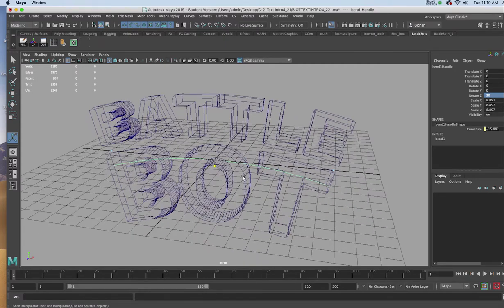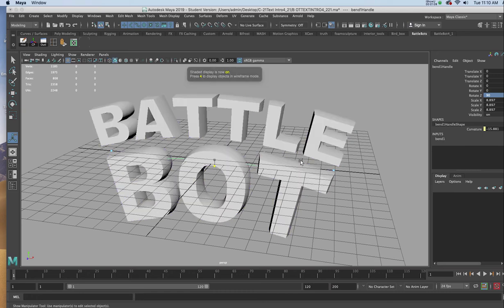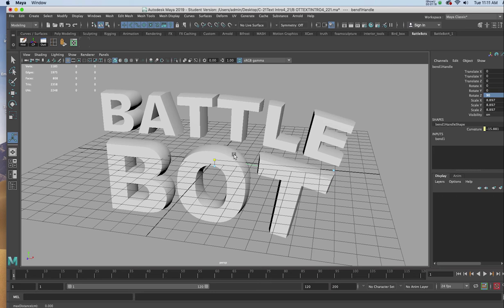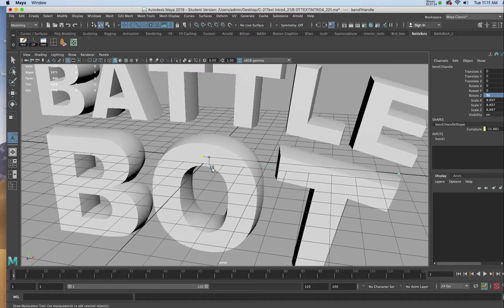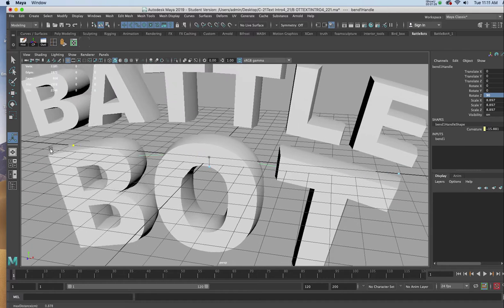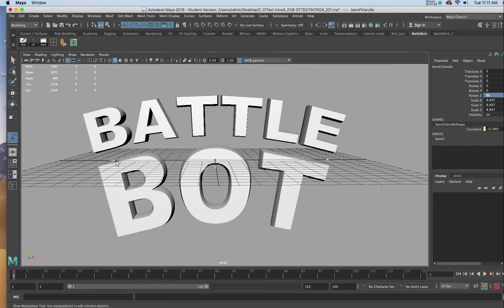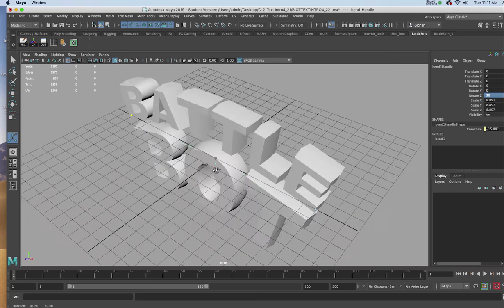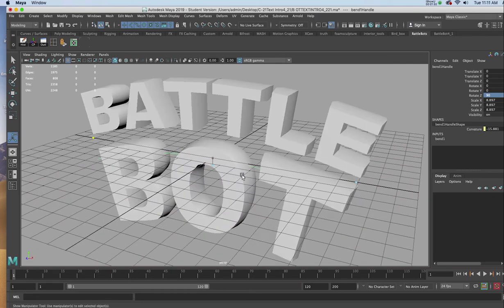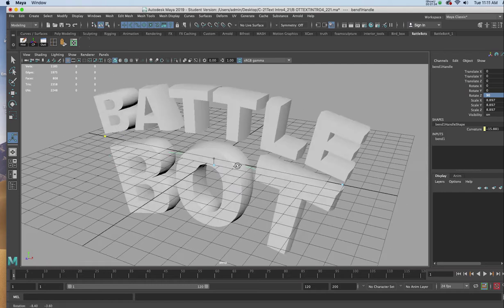You'll notice that with all these tools, there's some form of that green line, and all of them have this little diamond feature. And if I were to drag in on the one on the left, you can see the bend is being limited now to the right-hand side. The closer I get to the center diamond element, the less of the bend will be on the left-hand side. And this is pervasive in all of the deform tools, as we will see when we introduce the next one.